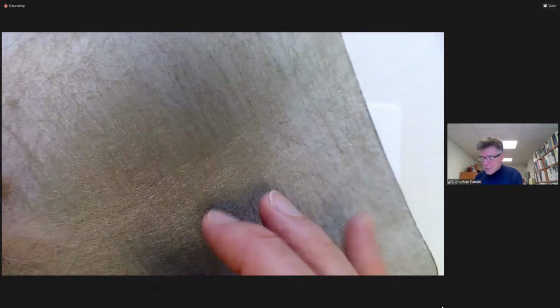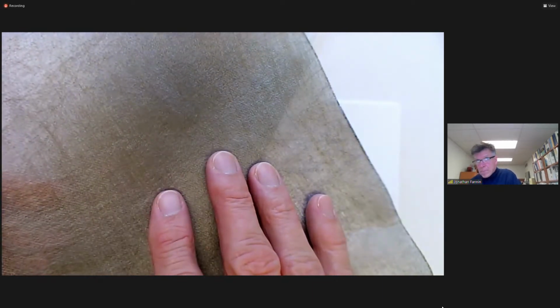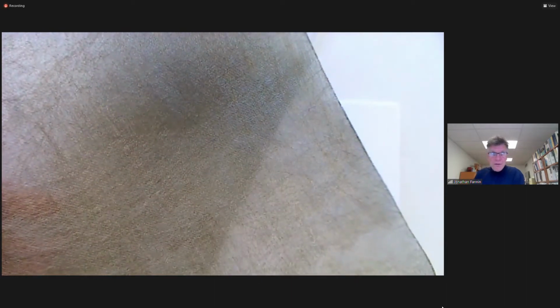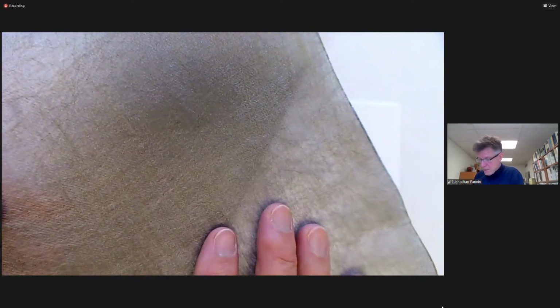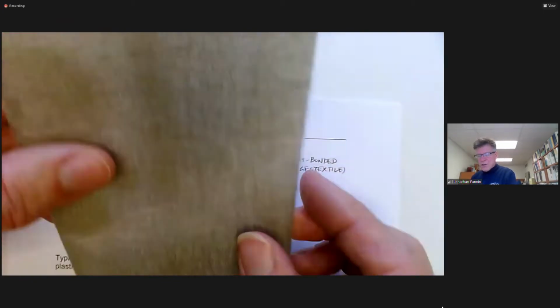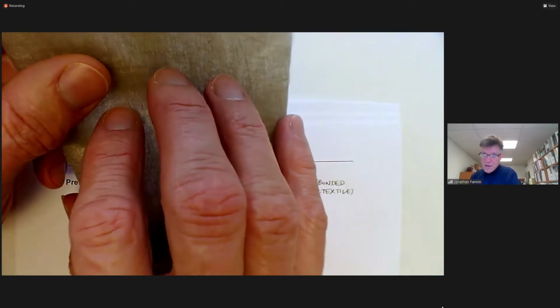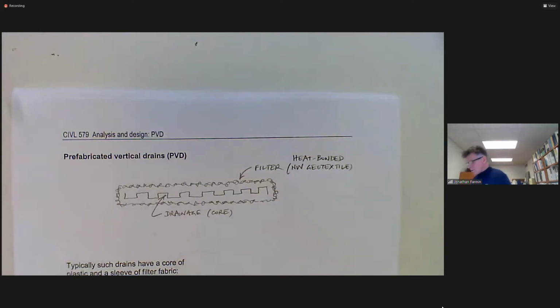And in fact, that's one reason why highways folks tend not to promote the use of heat bonded non-wovens in, I'll call it near surface alternating wetting and drying applications, just because of this tendency for water to pond on it a little bit. But that's less of an issue, I've got to tell you, and we'll see in some photos that once you shove it into the ground and it gets saturated very quickly and remains saturated, then it works just fine.